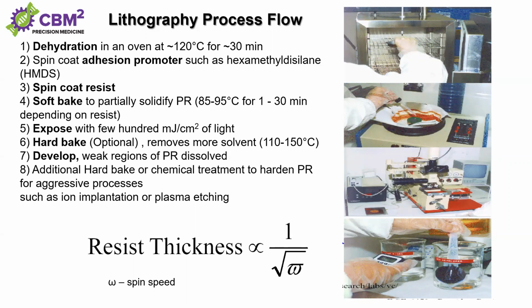By doing this, since normally during the photolithography process your resist layer is modified, this hard baking process cures that modified part of the resist, so that you have more durable patterns in your resist layer. Why is it important? Because if you want to go through the subsequent etching process or ion implantation process, you want to have a harder photoresist layer.